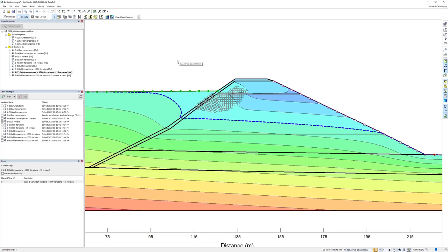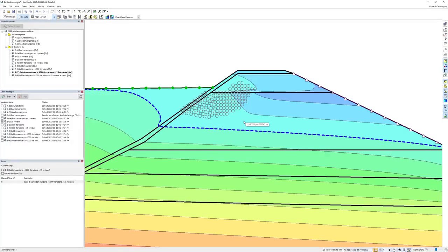Taking a look at our results in GeoStudio, there are no more red X symbols on the analysis. However, there are still some gray O's overlaid on the analysis results. As we had discussed earlier in the presentation, gray O's mean the first convergence check failed at the nodes where they are displayed, meaning there is still a bit of numerical instability in this area of the analysis.